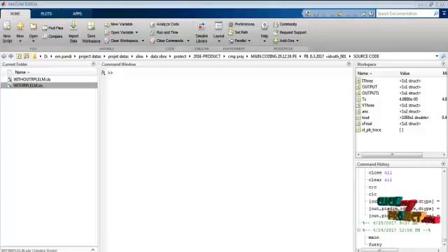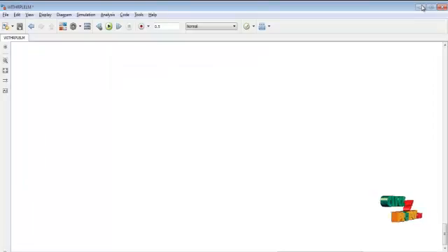Next, we see about the running process of our product. In this proposed implementation, the design is done in the MATLAB simulation environment. First, open a new model file. After opening the new model file, the main window will open. Then the elements are taken from the Simulink library browser. From the library browser, two main blocks are used. One is the SimPowerSystems block, and another is the commonly used blocks.